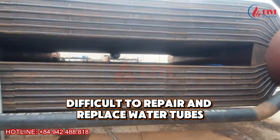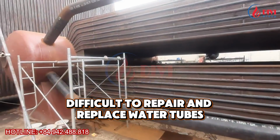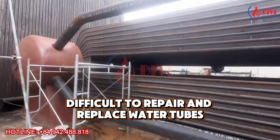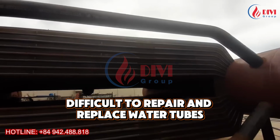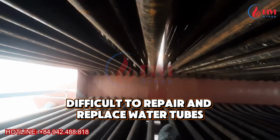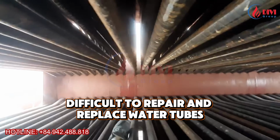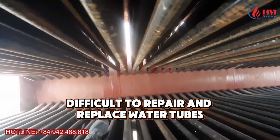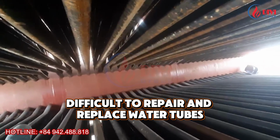In a two-drum water tube boiler, if a generating tube in the convection bank becomes damaged, a common emergency repair is to isolate that tube by plugging both ends. If only one or two tubes are affected, this temporary solution may be acceptable under certain operating conditions. However, if too many tubes are plugged, the available heat transfer surface is reduced, resulting in lower boiler capacity and reduced efficiency.